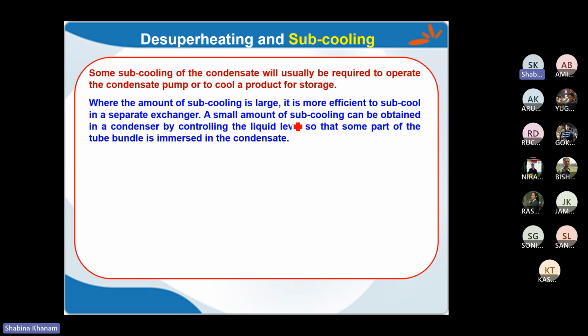Okay, so where the amount of subcooling is large, again the same thing, more than 25% of duty of condenser or latent heat of the condenser. If amount of subcooling is large, it is more efficient to subcool in a separate exchanger. Okay, so in that case you need to consider the condensation in different exchanger and subcooling in different exchanger.